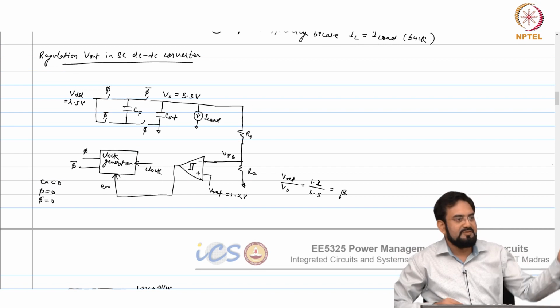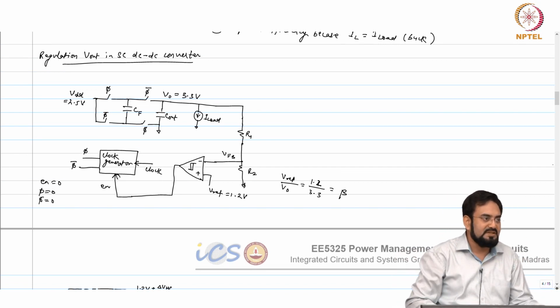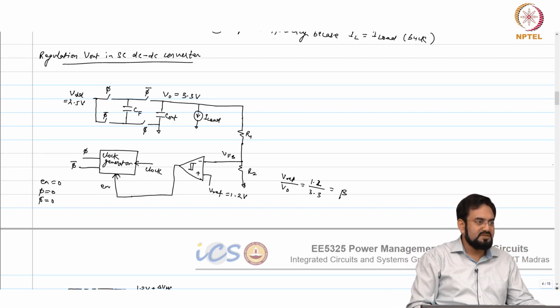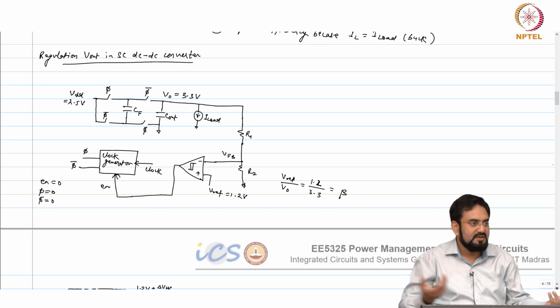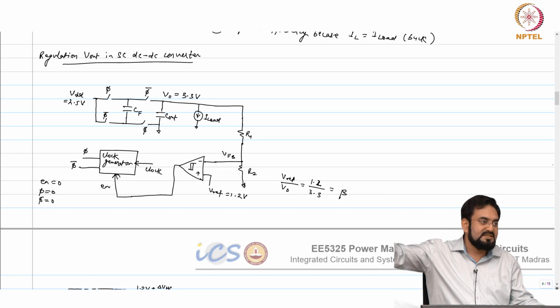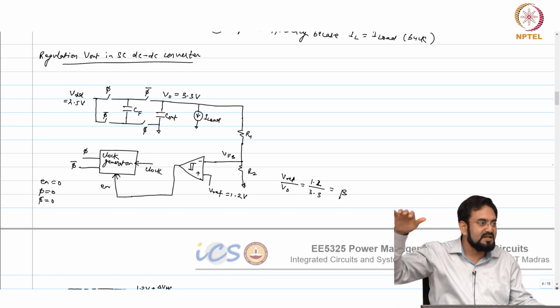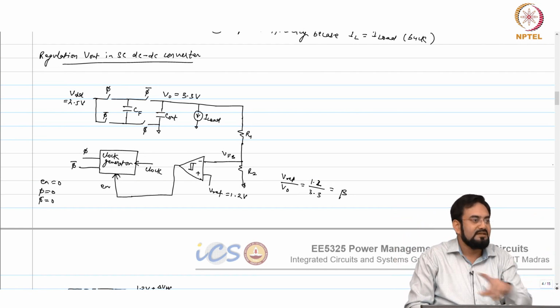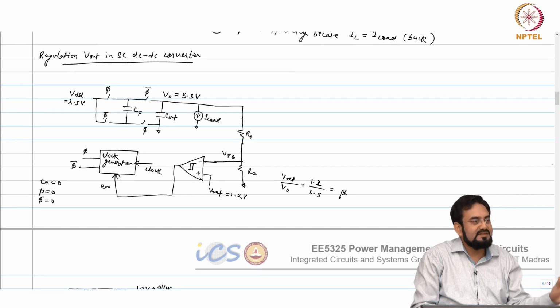The current drawn from VDD to output in a steady state will be 0 under no load condition. But if it never goes to the steady state voltage, you are still charging the output cap. So there is a current in the path, and it will always incur I square R losses.